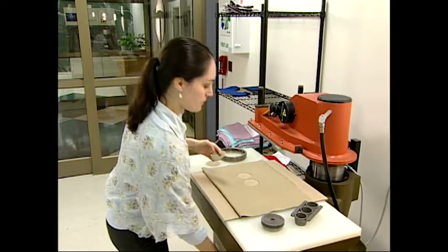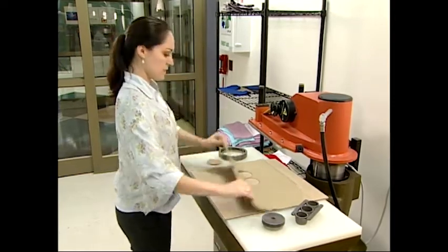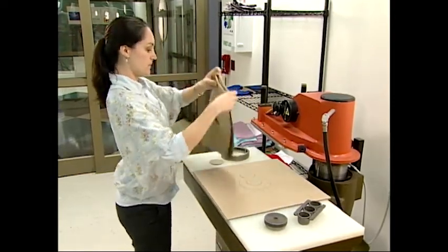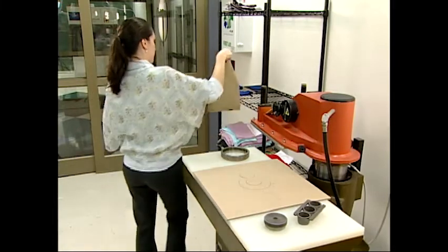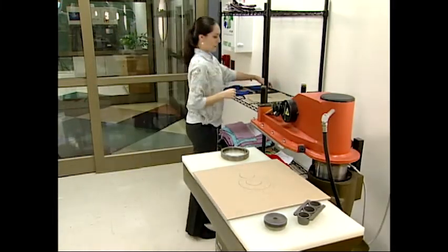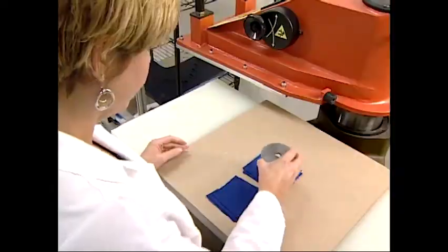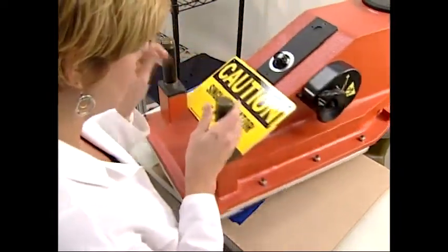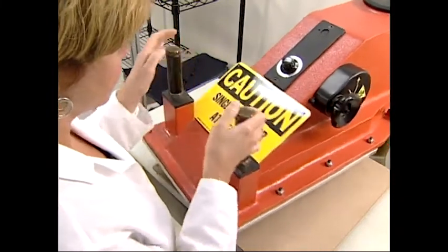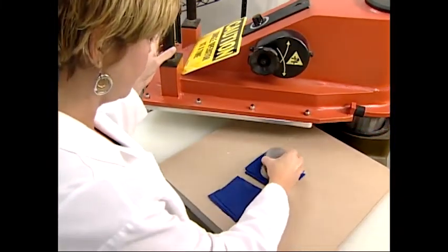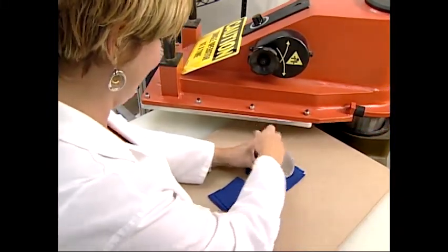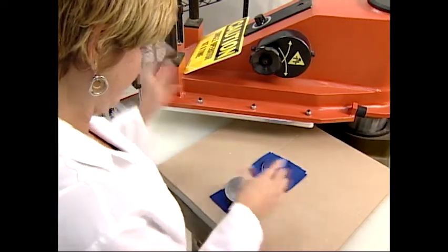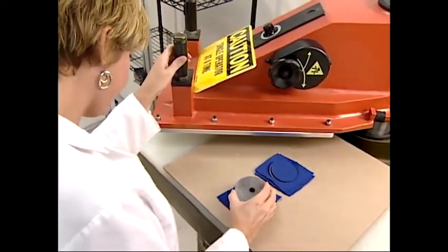The most common manner to sample these small specimens is with a cutting die to cut specimens from different locations in the sample. Either square or round dies are available for this method. Some die cutters are designed to allow for a direct reading of weight using a scale that weighs in grams. The size of the die circle is designed for this purpose. In these systems, 1 to 8 circles are stamped to give a direct reading.